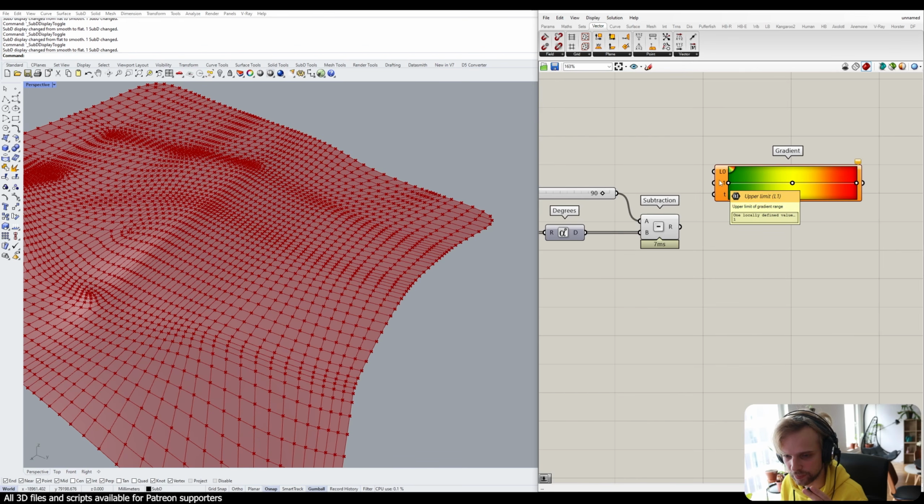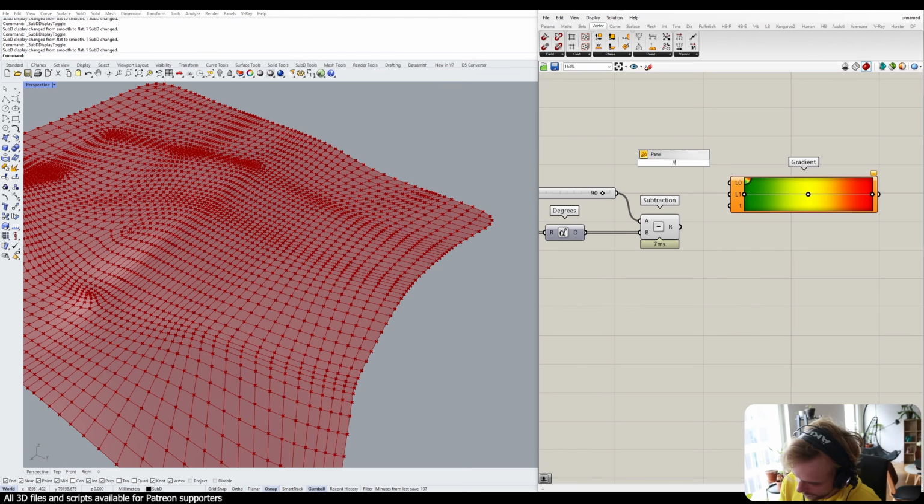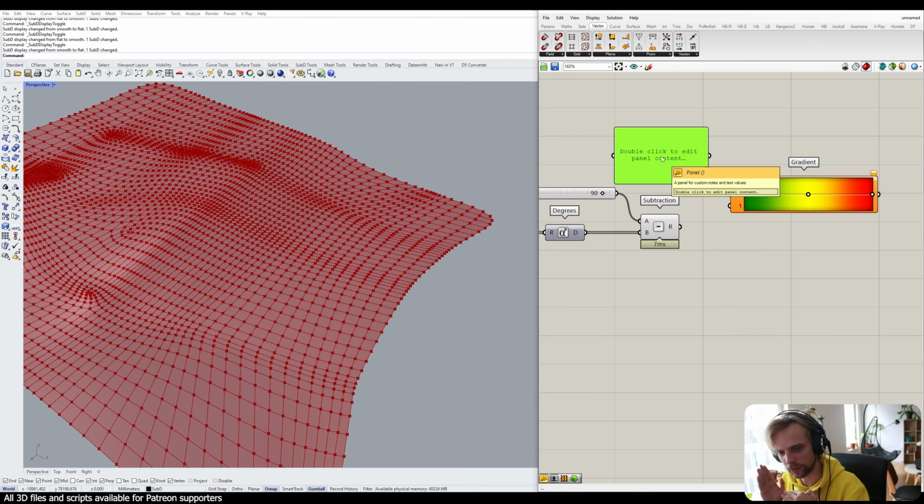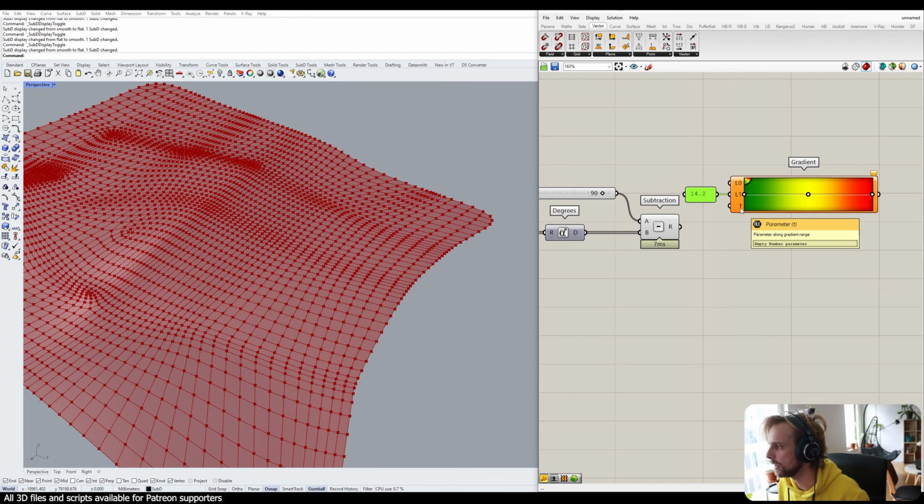What's bad? At which color do we say that it's red? Well, the bad number is whatever gradient you have set as a limit, right? And in our case, it's 14.2 degrees, as I mentioned before, 14.2. Different sites have different specifications. This one has 14.2, right? So that's our L1. And then our parameters are all of the degrees that we have for each of the points, like that. And thus we get the colors.